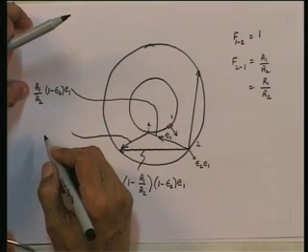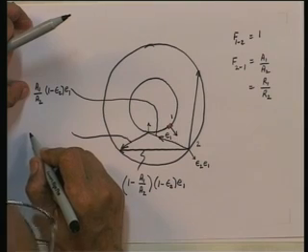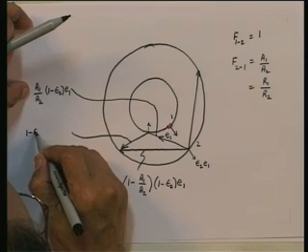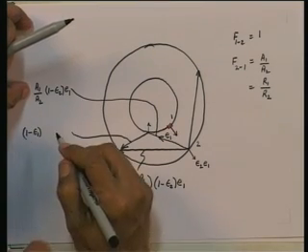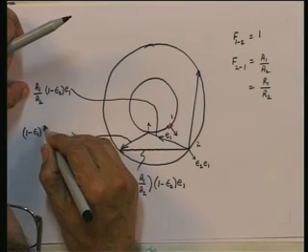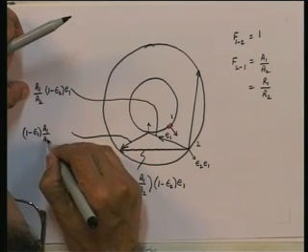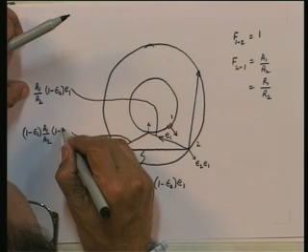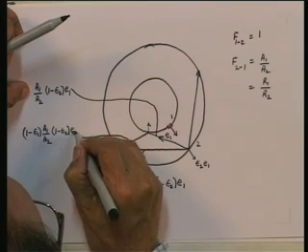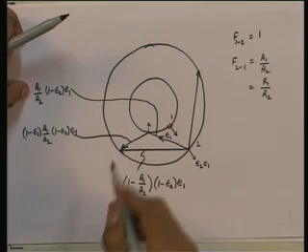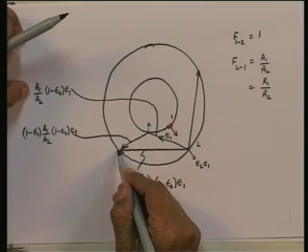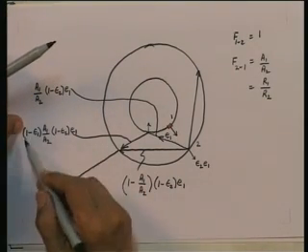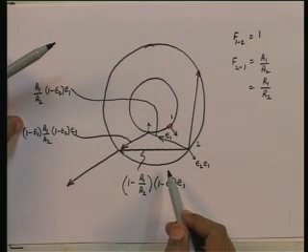So, it will be 1 minus epsilon 1 multiplied by A1 upon A2 multiplied by 1 minus epsilon 2 into E1, and out of that the quantity that is absorbed will be this quantity which I have put down here multiplied by epsilon 2.